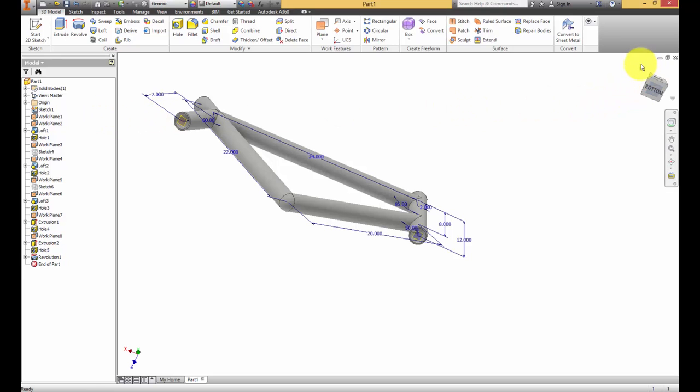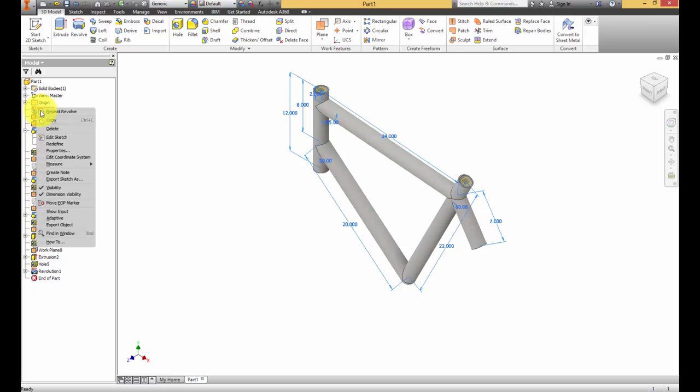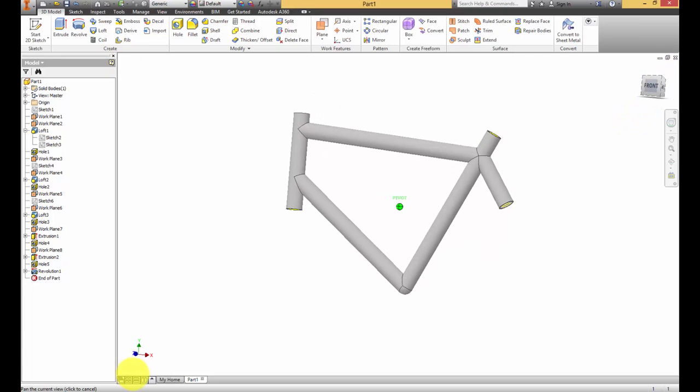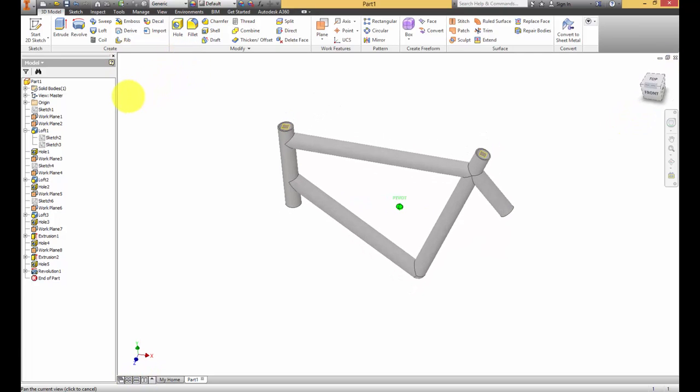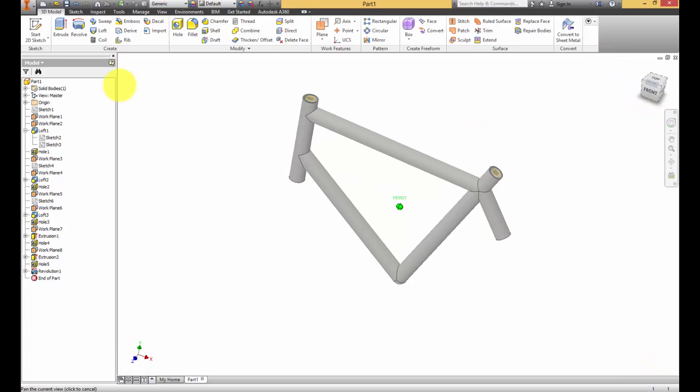We always want to try to clean up our sketches, our models. So we're going to take this sketch. If I expand the browser bar, you can see which sketches I've got for what. And we've reused sketch 1. I'm going to right click and take the visibility off of that, and it cleans it up. I'm going to leave all these planes. Most of them are not visible or won't be, but we may use them for when we begin our assembly.